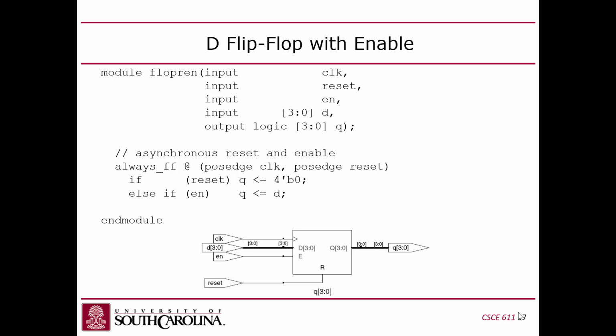If you're trying to design combinational logic with an always, you have to make sure you set all the output signals every time that always statement is activated. So this is a problem if you have an if statement inside your always: you may accidentally infer a latch if you don't assign all the possible outputs from every path of the if statement.